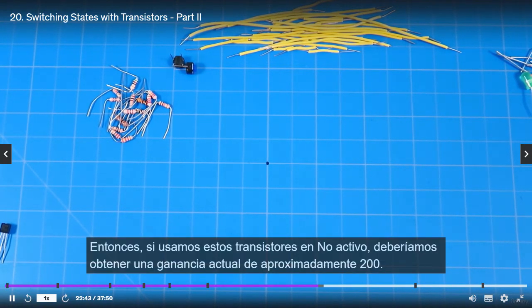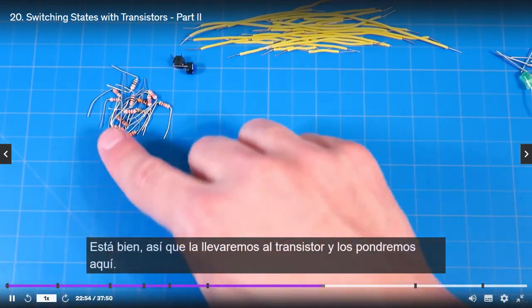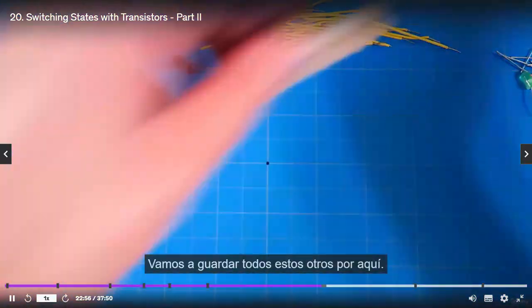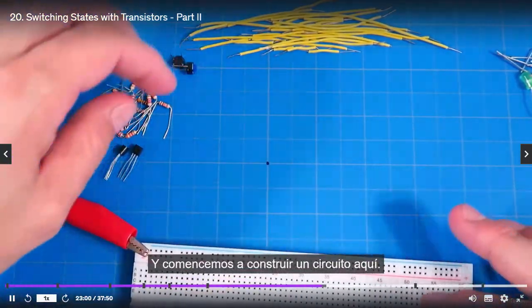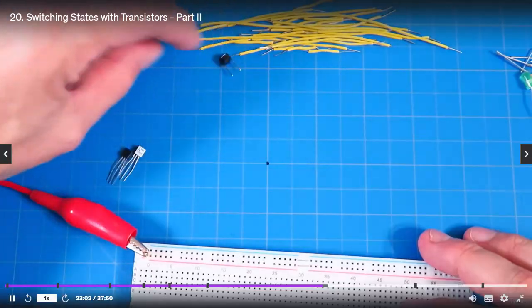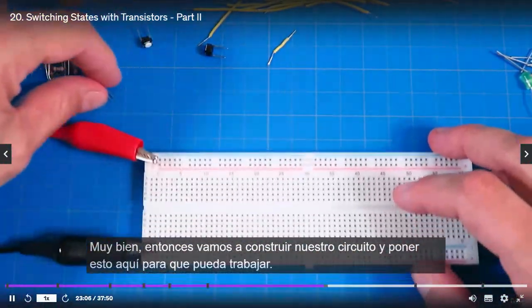So if we use these transistors in active mode, we should get a current gain of about 200, all right? So that's the first thing to note. All right, so we're going to take our two transistors, we're going to put them here. We're going to put all these other ones over here, away. And let's start building a circuit here.